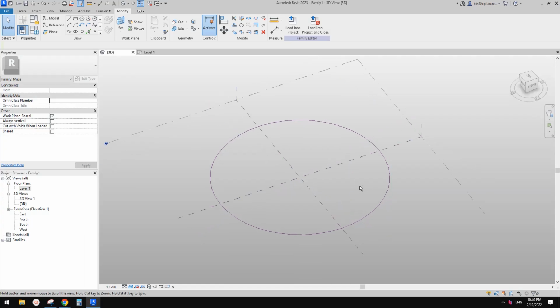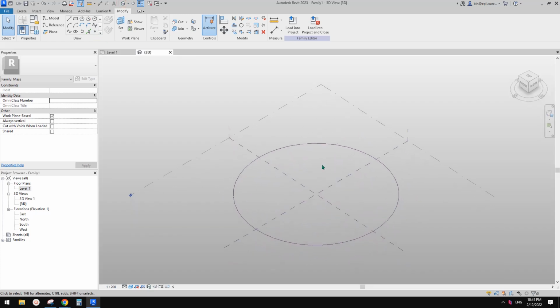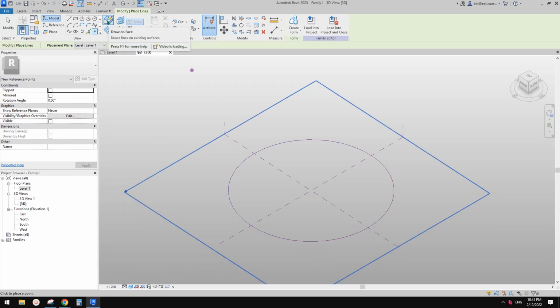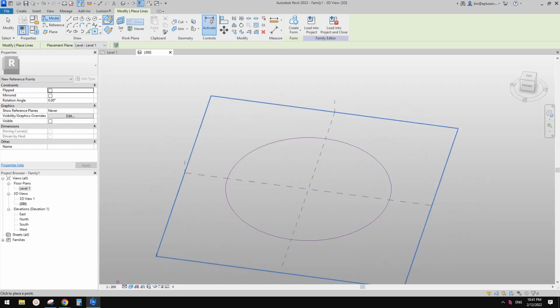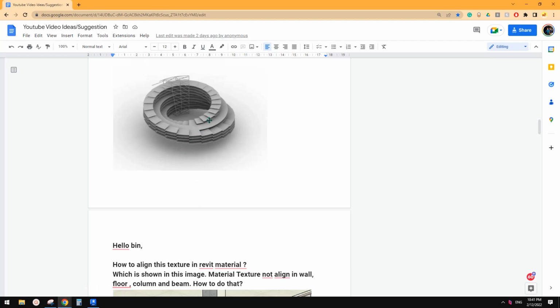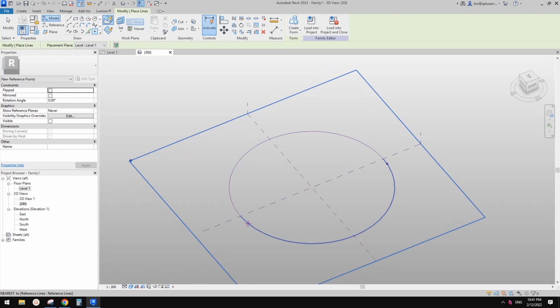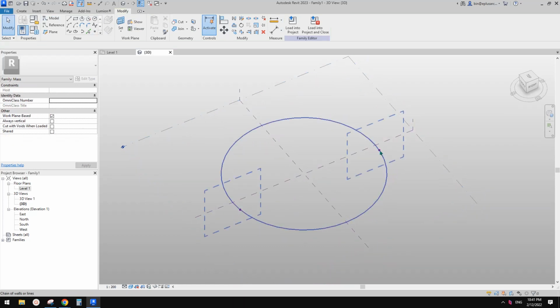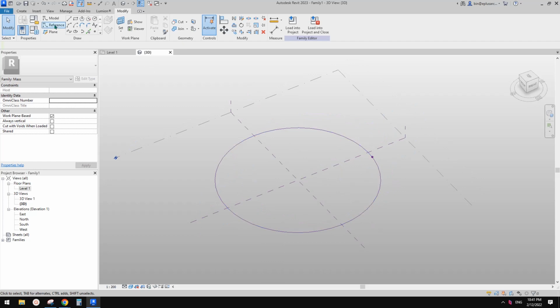So let's go to Revit. I am just going to do it in 3D view. Okay, so place point, draw on face. And I'm going to place it in the middle, I think. Hang on, let me just think. Where should I place? Okay, so this will be where the 3 are vertical, and at this point it will be 1 2 3 horizontal. So just place 1 point and just create a reference.